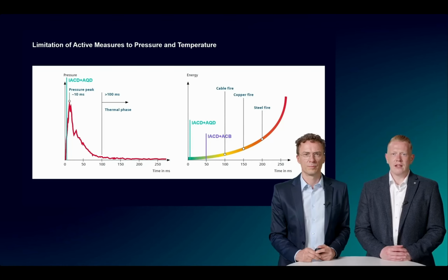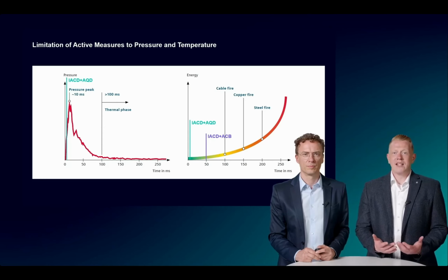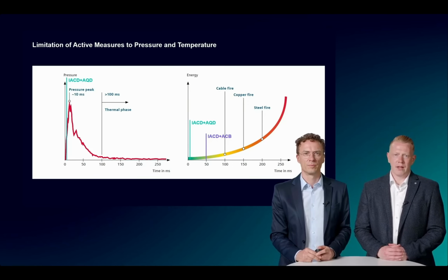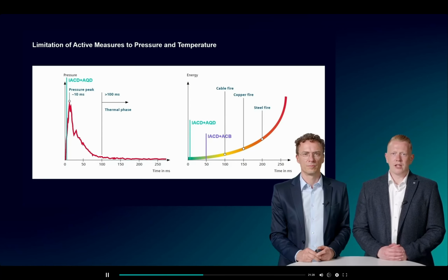The next point we have to consider is neutral earthing. And the question is now, what impact does the quenching device have on protection? Well, what we see here is a device that causes an all-pole short circuit on the main bus bar, on one side of a transformer. This short circuit immediately removes the energy from the arc fault, and the arc goes out. The resulting short circuit is now switched off by the circuit breaker.